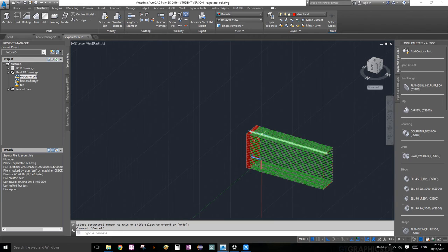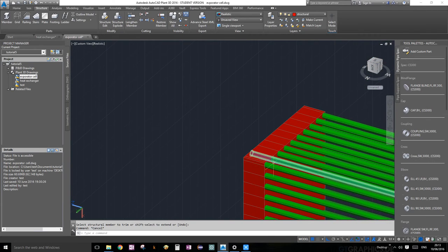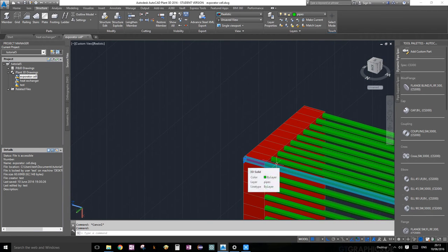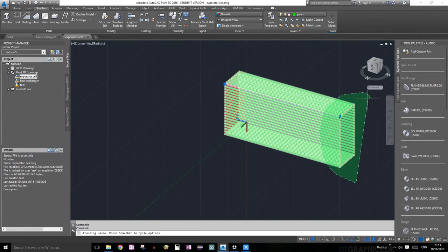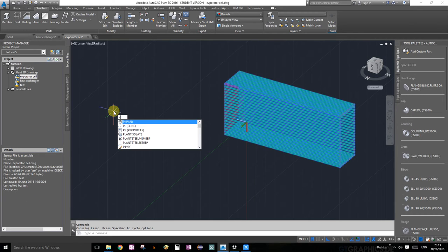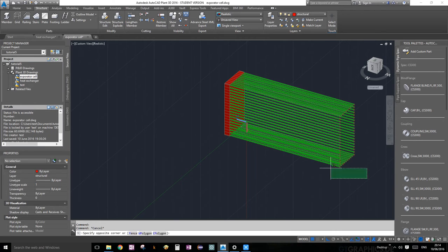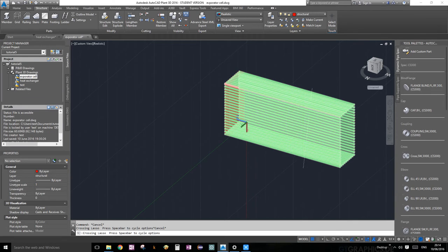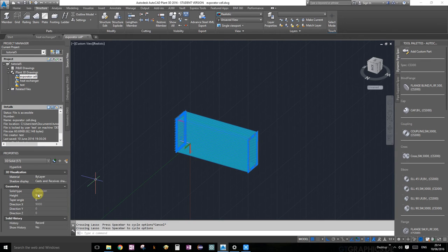You guys can cut it each one by one, or we can just shorten it one by one. It all depends. Or we should have probably, when you drew your pipes, you could also define. Actually, you know what? Let's try to see if we can change it through our properties window. So select all the pipes. Oh, and the properties window is not open. Go ahead and start typing properties, and here's our properties window. No selection, it says. Of course there is some selection, buddy. Okay, I don't want those red little things to select as well, so I'm just going to select just the pipes, and let's see what sort of information I get here.